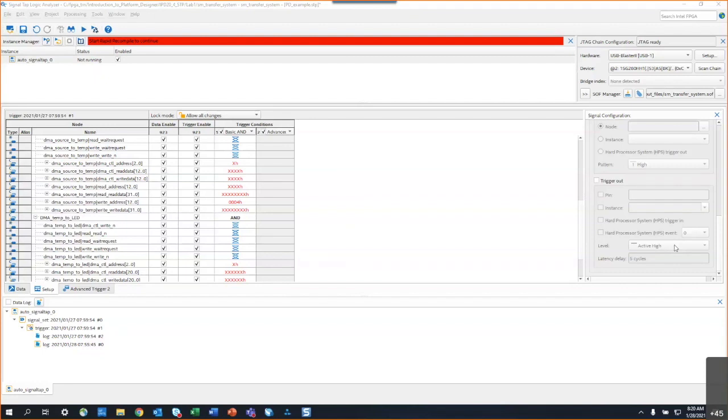Sure. Yes. So I have my ADC data coming in. The clock is the 125, and the SignalTap is running at 250 megahertz. That means it's twice as fast as the ADC clock. So when I look at the traces, I would expect after 2 sampling clocks of the SignalTap, the ADC data to change because it is running at half the rate, right?